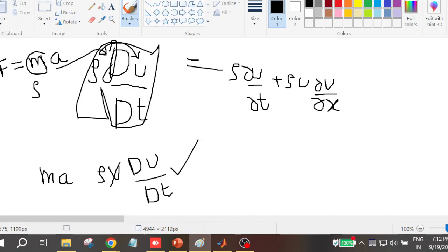The changes will happen on the right hand side where there are diffusion terms. Basically, in tau xx, or as you call it sigma xx, you take it as minus p plus 2 mu into dou u by dou x, right?